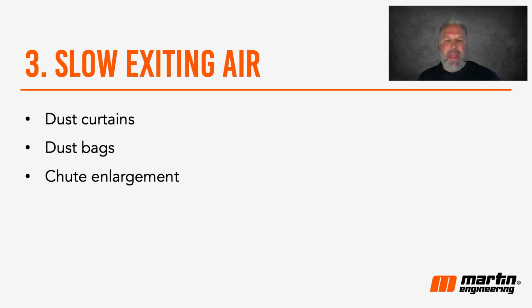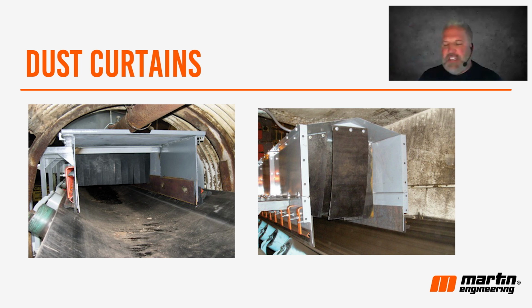If you can use a dust bag along with dust curtains, you'll really improve on your air velocities and knock that dust down. We're going to talk about each one of these separately, but we're also going to talk about all 3 maybe used together. So, dust curtains, a pretty simple strategy here. You've seen this before. If you've ever tried to combat dust, this is probably one of the first techniques that people will do to reduce the airspeed coming out of a transfer point.